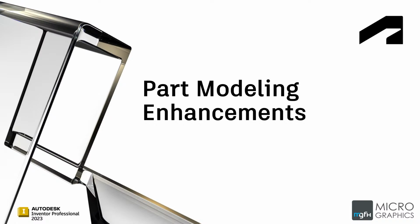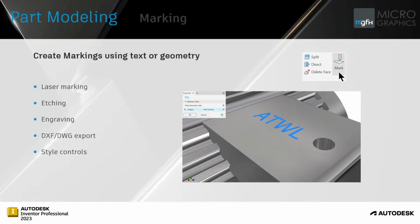Now let's take a look at part modeling enhancements. Okay, first up in the part modeling environment, we have a new marking tool. We can create markings using text or geometry that you have drawn in a sketch. This can be used for laser marking, etching, engraving, and also export that to DXF and DWG with style controls available. So basically you can use any sketch with a text or a geometry to create a marking.